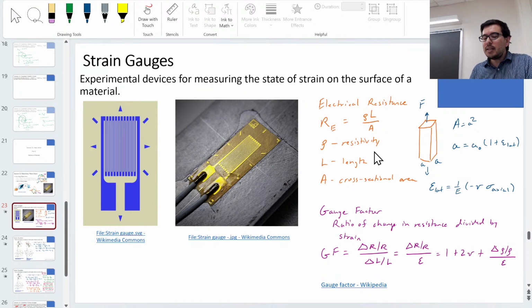It turns out that it's not just about the change in cross-sectional diameter with the materials that are typically chosen for this. You get increased sensitivity from a piezoresistive effect, so that the resistance actually changes. The strain actually induces a higher change than just the cross-sectional area changing.